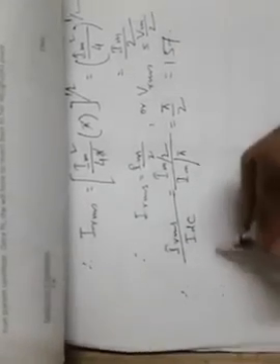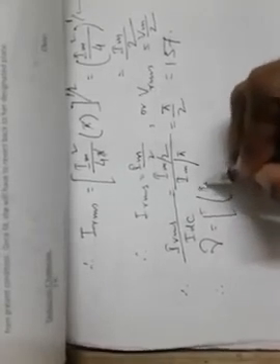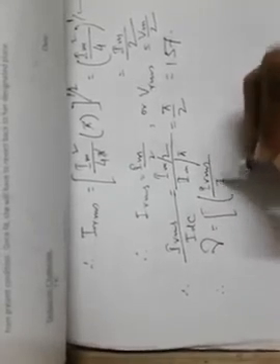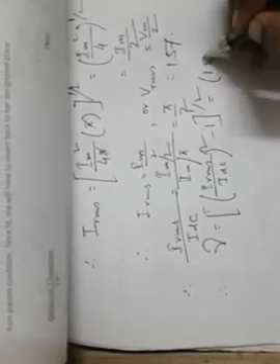So now the ripple factor gamma is equal to (IRMS by IDC) square minus 1, whole to the power half, that is (1.57) square minus 1, whole to the power half, which is 1.21.